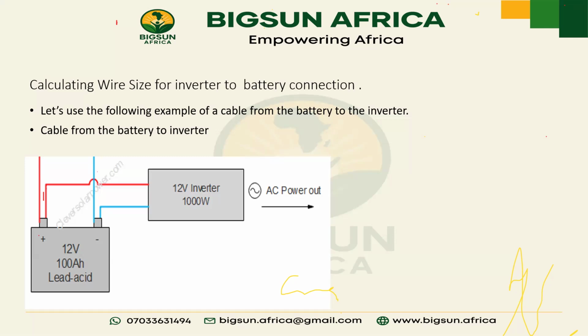You say that the distance between them we are using is 3 meters, right? If we are connecting these batteries in parallel, that means we are going to have 12 volts as our total voltage, right? Are we together? Yes, sir. 12 volts, 400 amp hours. 100 is going to be 100 times 4, which is 400 amp hours.